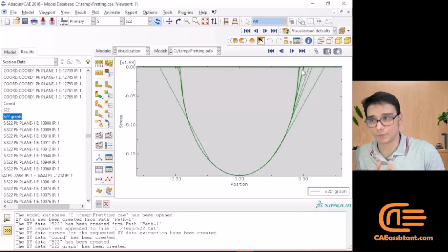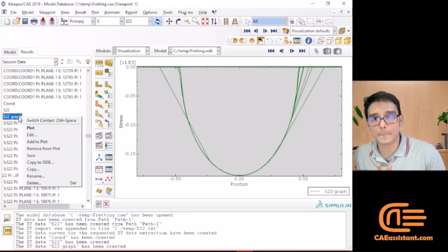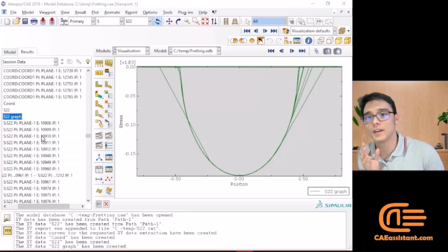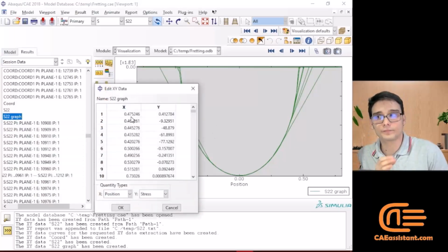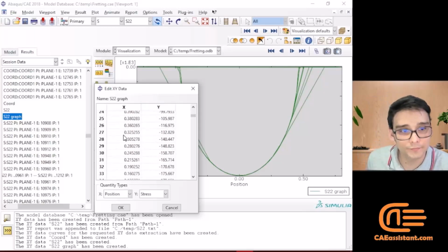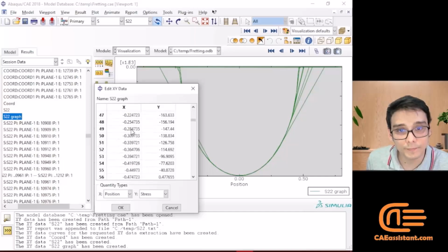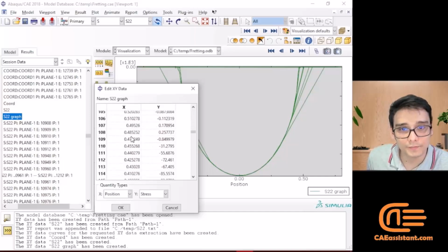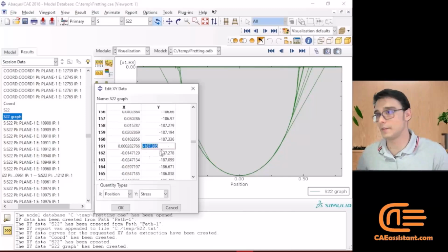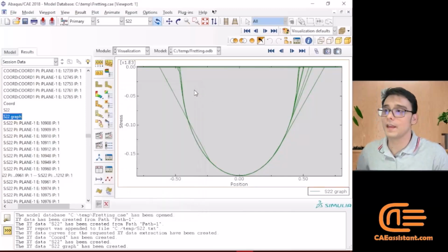The only problem of doing it like this is that it is not going to be correctly distributed. It is not going to be in order, but it is going to be more accurate since it is going to get the integration point values of the stresses. So for example, let's try to find the middle. Here, for example, this is the middle, this is the value that we got. However,